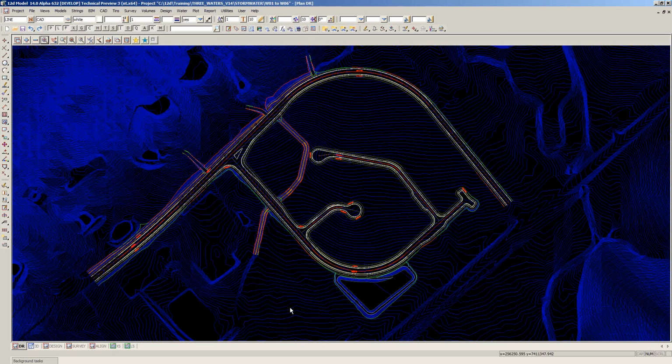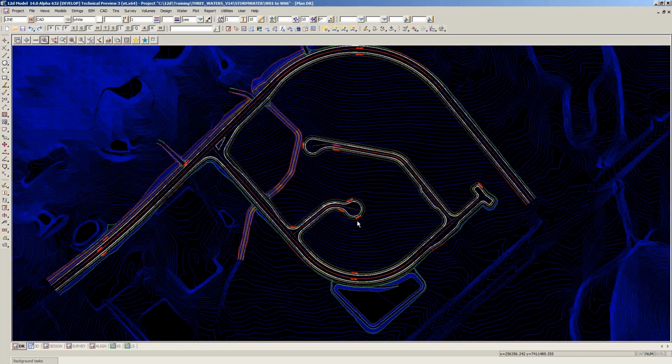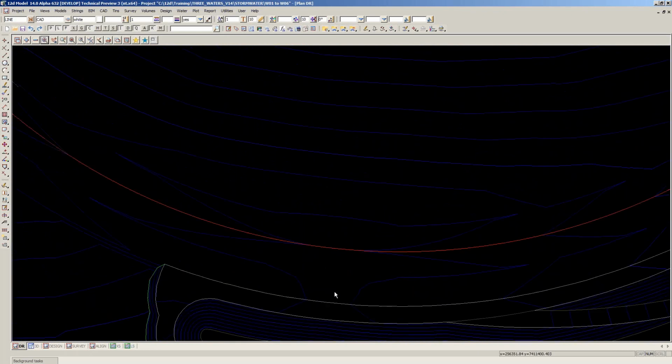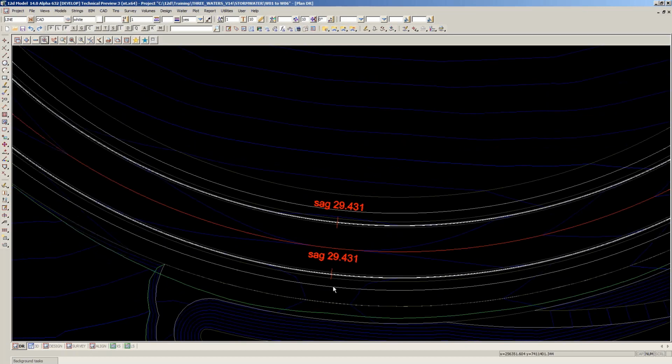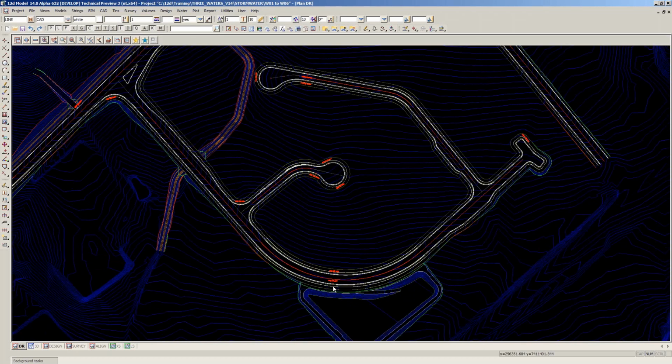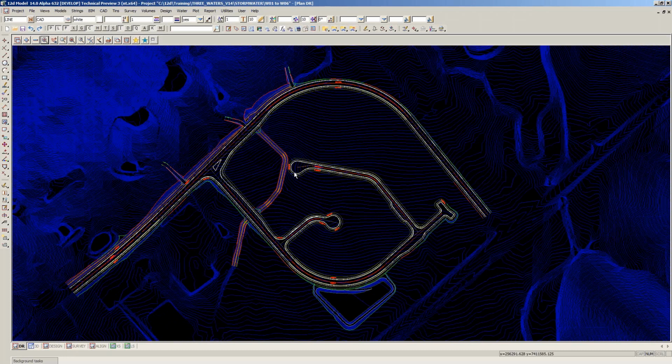And when we talk about running the downhill strings, we're typically wanting to process our design strings, which are the strings I've got on the screen here. I've also in advance labeled the high points, the crests and sags, the high points and low points on the drainage inverts, the curb inverts and the channel inverts. So that's what the little bits of red text are marking out. There's a couple of high points there, a couple of low points there. Around these curb returns, there's crests and sags and what have you. A couple of the curb returns have markers as well, and so forth. So that's where we're starting today.